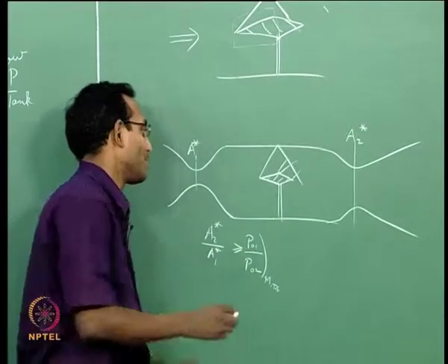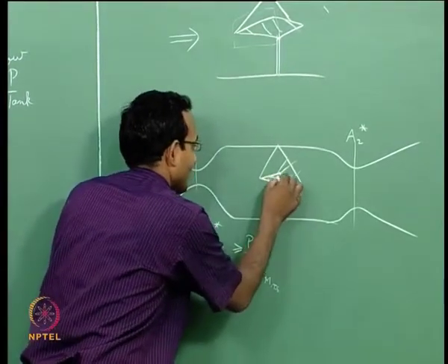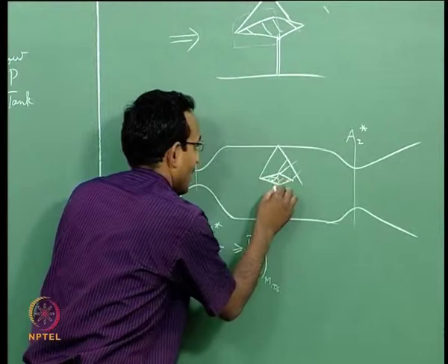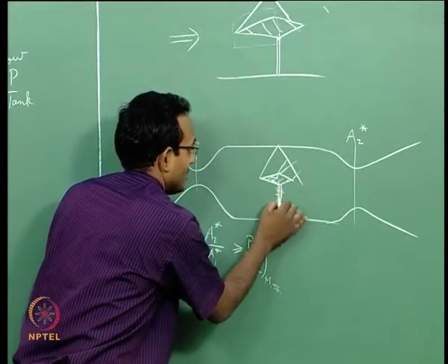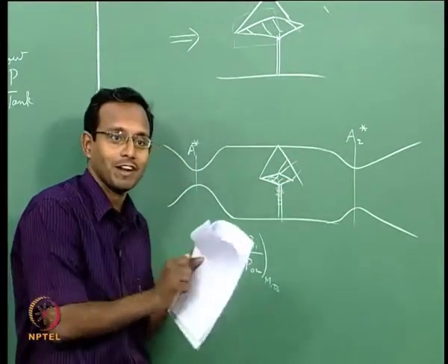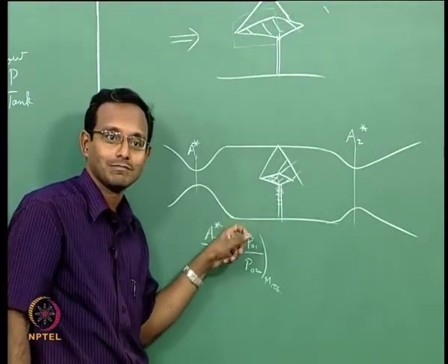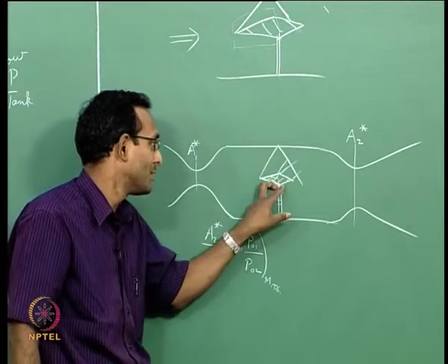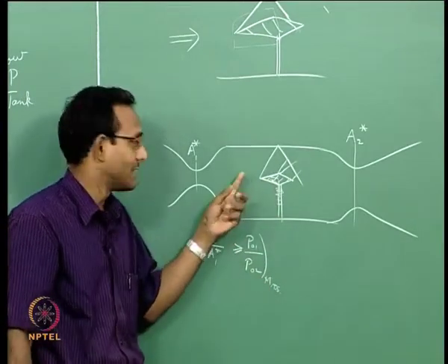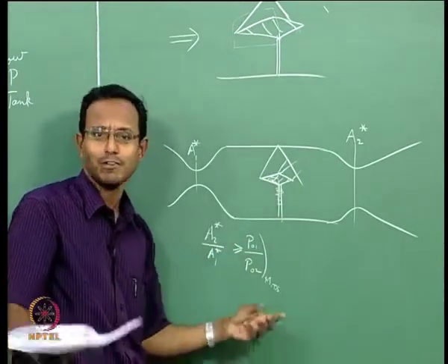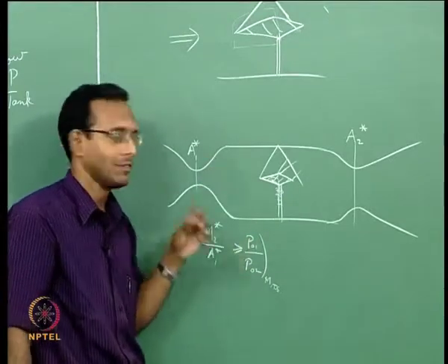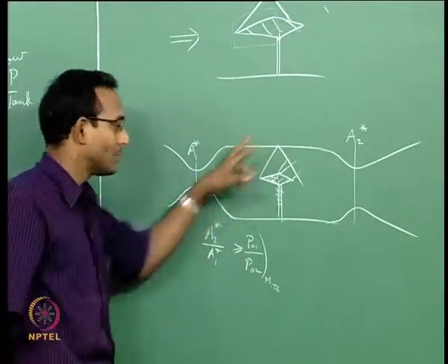Now if I have to think about, I have pressure transducers on this and there are wires going through, and the wires I have just wrapped around this, let us say, with some kind of tape. Even that total cross section matters. Typically what they do is they put this holder as a tube and take all the wires through it. May not be always possible, but most of the times they do this. Okay. All those things matter.